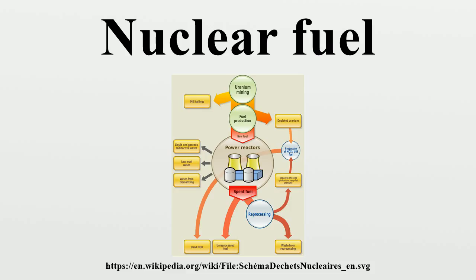In modern BWR fuel bundles, there are either 91, 92, or 96 fuel rods per assembly depending on the manufacturer. A range between 368 assemblies for the smallest and 800 assemblies for the largest US BWR forms the reactor core. Each BWR fuel rod is backfilled with helium to a pressure of about 3 atmospheres.